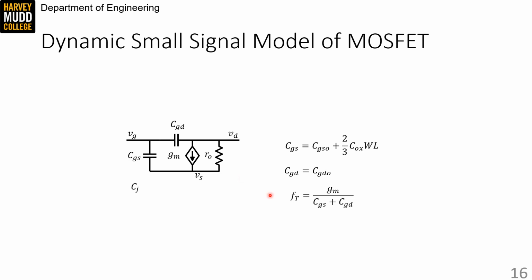And we indicate that because the approximation we used in our earlier fT equation has been replaced by an equality here. Also, note this is the equation for radians per second and not hertz, so that's a little bit of a misnotation. However, we've also forgotten a terminal in our quick small signal model. Don't forget that we still have junction capacitances to our body down here.